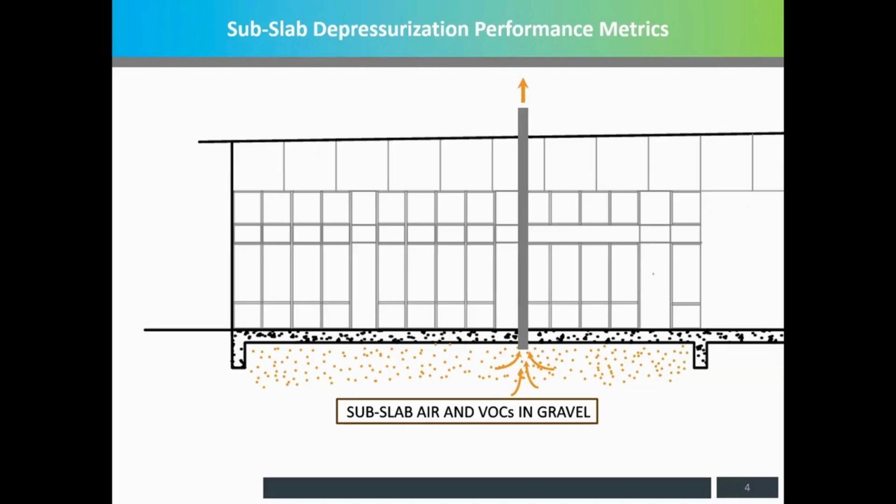But to be 100% effective, an SSDS needs to overcome advective and diffusive flux. You need to know what amount of negative pressure is necessary to overwhelm all of that. And that's what these downward arrows represent. They're a counterflux, if you will. And if you can do it, you sever the exposure pathway. For severed exposure pathways, the attenuation factor becomes 0. Or with SSDS, you might end up just attenuating the vapors. You can calculate that too, but we don't have time for the math.